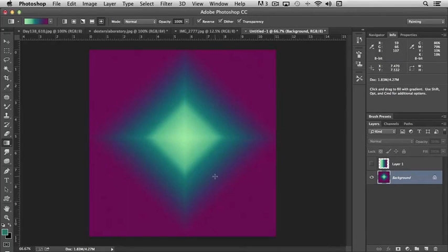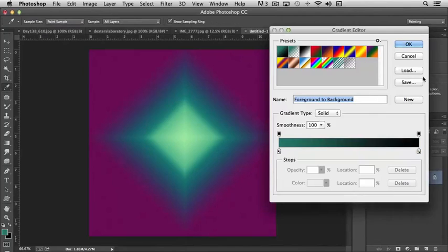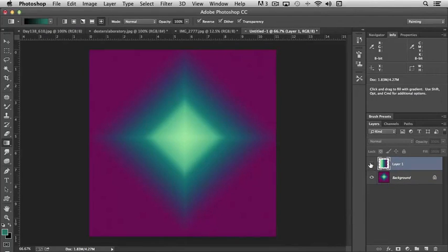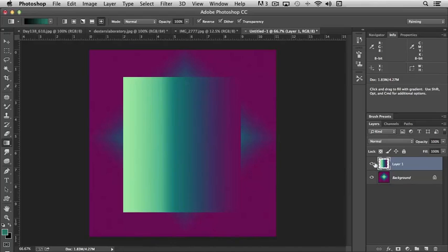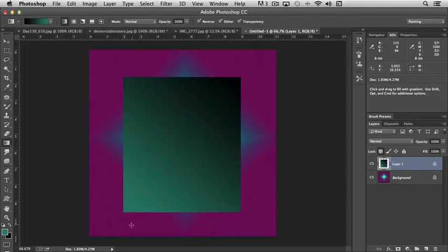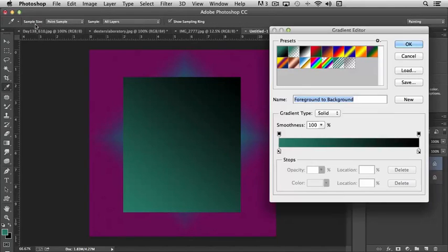Okay, so as you would imagine, this effect using these gradients can be applied in a lot of different ways. And of course, you can play around with subtlety. I mean, we're using kind of extreme colors, but more times than not, you're going to simply just use the foreground and background color. So if I highlight this particular layer again and lock it, actually, let's go with the linear blend. I can apply this new gradient just to the box because I have that layer locked and I selected this color. Okay, just the foreground and background.